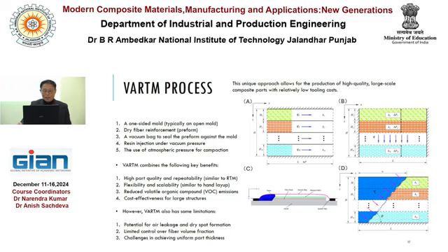But this VARTM also has some limitations, because of the potential for air leakage and dry spot formation. Dry spot formation means the preform, the fiber, was not wetted. In the case where, after ejection, we find dry spots, there's no resin at all.